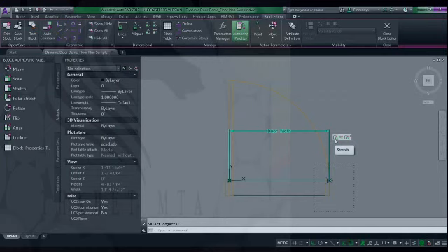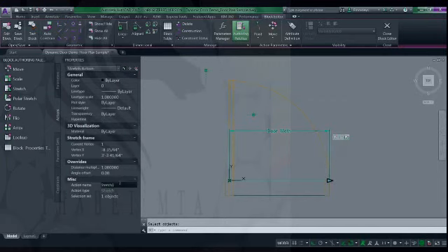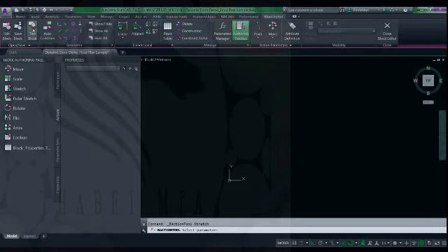So if you hover over it, it gives you stretch or stretch one. You can rename this as well, so I'm just going to go ahead to further customize it and just name it stretch dash panel, and then I'll just do stretch DW for door width. All right. So now let's see how it looks in test block so far.